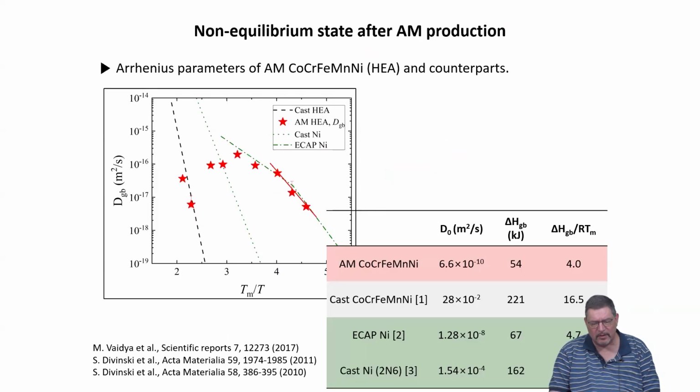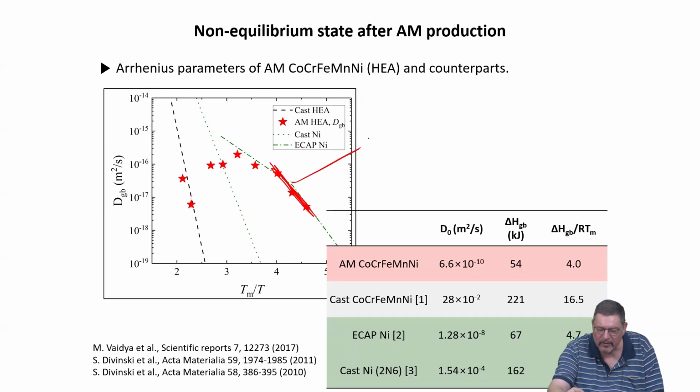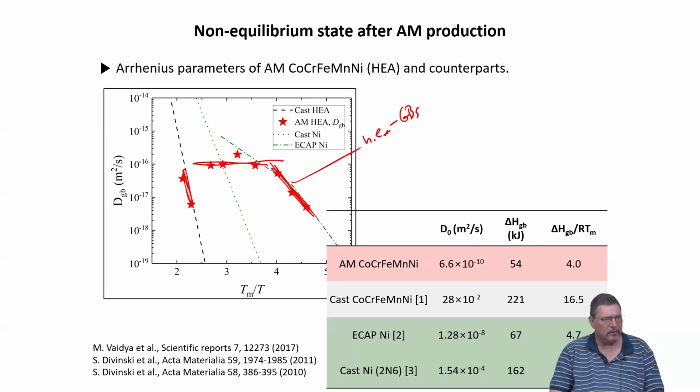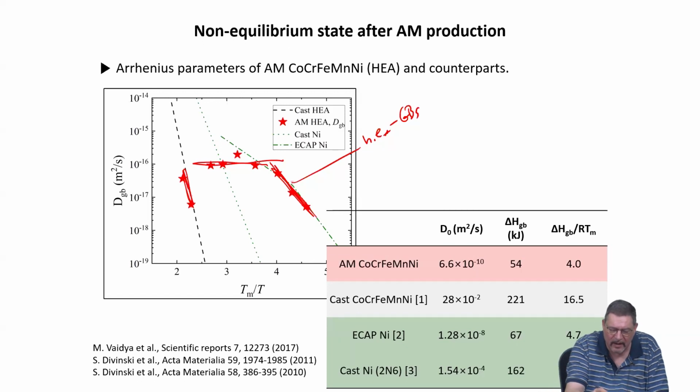And again, you see here it's also following similar trends, right? So you have, at the low temperatures, a branch where you have very, very strongly different diffusion behavior in these non-equilibrium grain boundaries, then you have something like a transition regime where the boundaries start to relax. They go maybe to transient states, which also have a lifetime, and in the end they fall on the grain boundary diffusion coefficient values, which are also true for the relaxed random high angle grain boundaries.